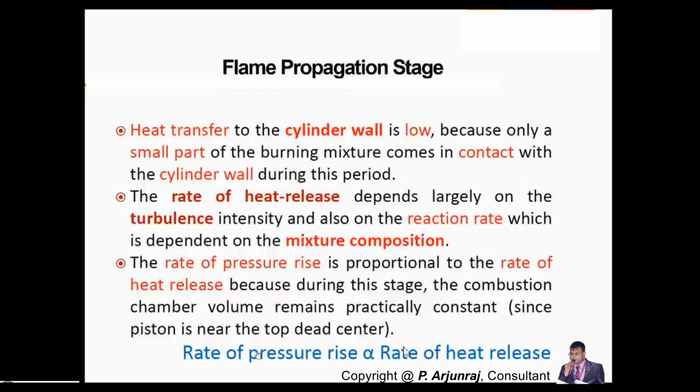A very important thing here is that the heat transfer from the piston to the cylinder wall during the flame propagation stage is going to be low, because only a small part of the burning mixture comes in contact with the wall. The burning mixture here is nothing but air and fuel. Only a very small part is going to come in contact with the cylinder wall.